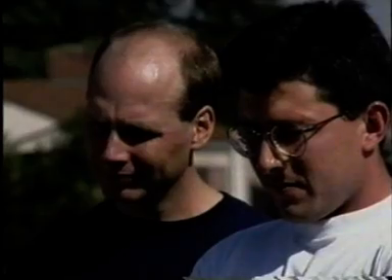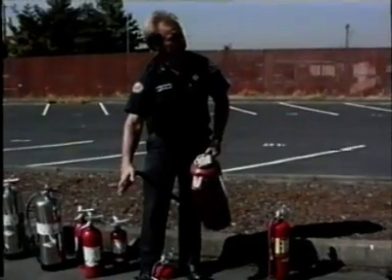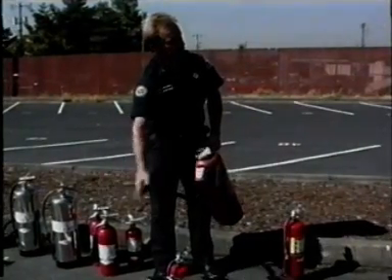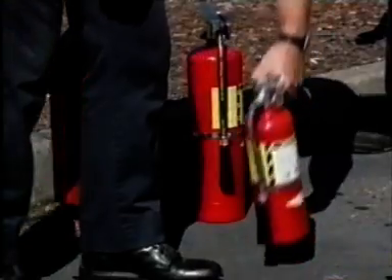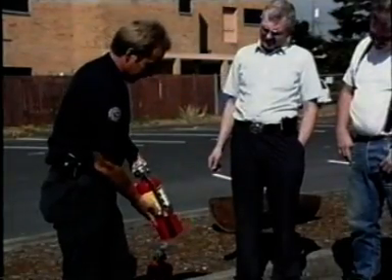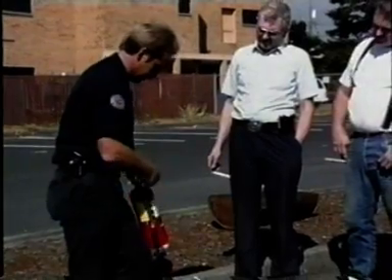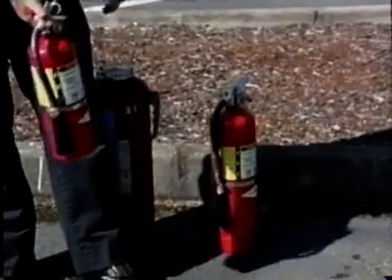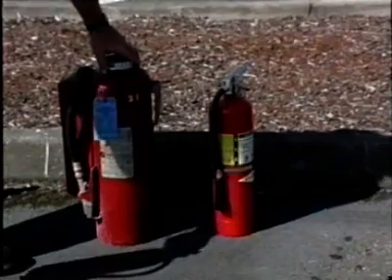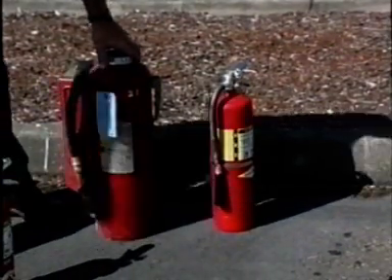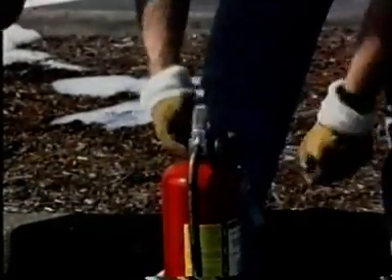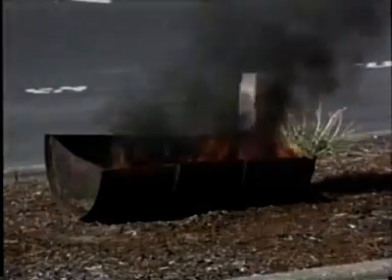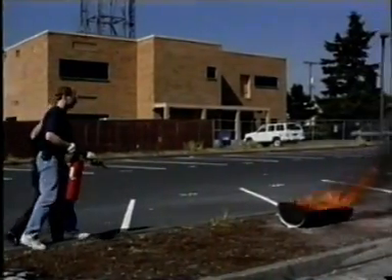As the name implies, the agent inside a dry chemical extinguisher is a chemical that comes out in a dry, powdery cloud. To operate a dry chemical extinguisher, you first determine if it is a stored pressure type, which looks like a stored pressure water extinguisher, or a cartridge-operated type, which has a separate agent tank and pressure cylinder. To operate the stored pressure type, simply pull the pin and squeeze the shutoff handle, and the chemical will discharge.